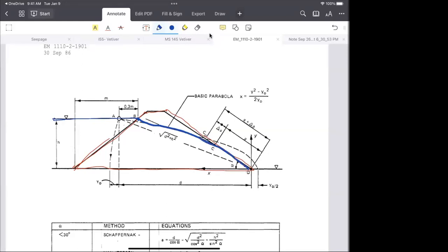Like this. That's the most typical line. You run any analysis, you will get a flow line that looks like this. In this, there are a few different points: B, C, D, and A. There are 4 different points that we need to graphically establish the seepage line. So this is the seepage line, the top of the flow within the dam.